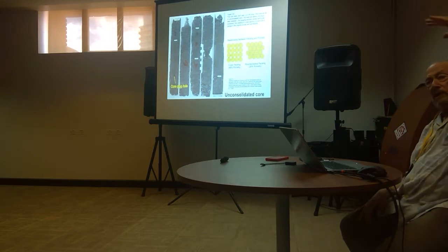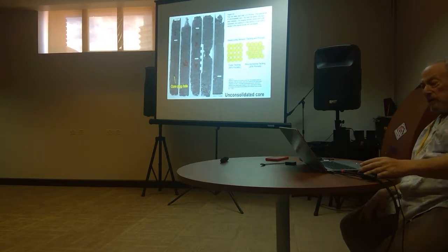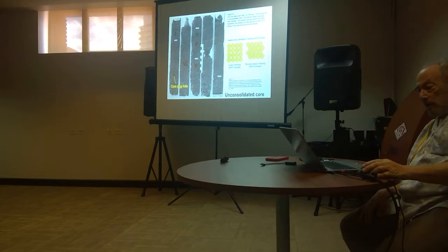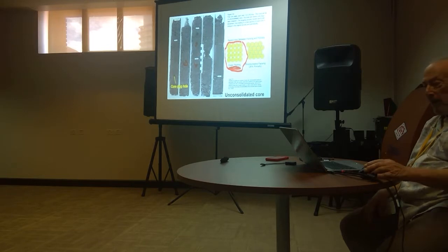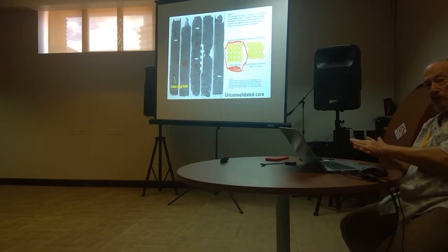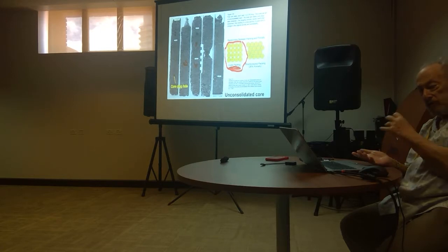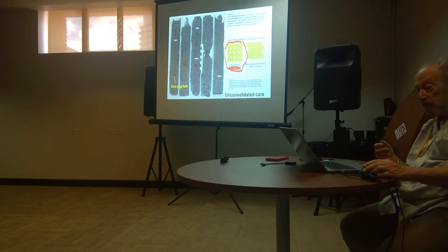Well, when that sand was originally deposited on the seafloor, the grains were like this. They were in a very unstable position, and in fact you had a porosity of 48%. But with a little bit of compaction, you're going to rearrange those grains into a more stable configuration.